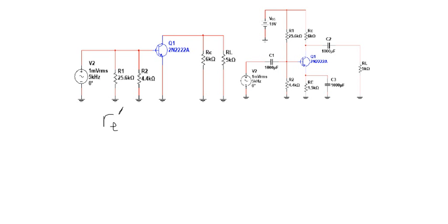That is a resistance that's internal to the base emitter circuit or junction of the transistor. And it is typically going to be equal to 25 millivolts divided by the DC emitter current that we found from the DC equivalent circuit. We saw how to do that last time.